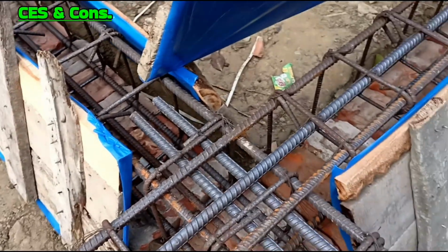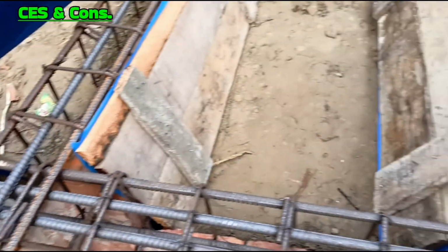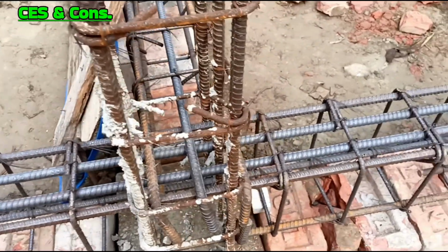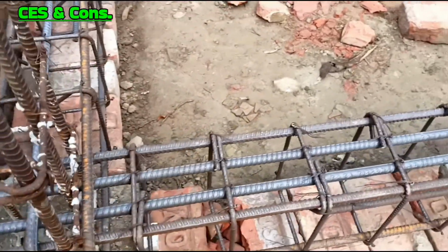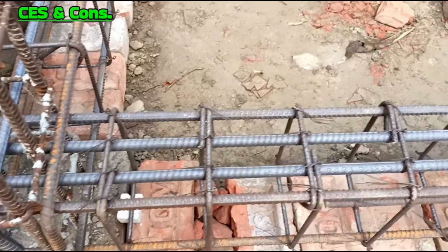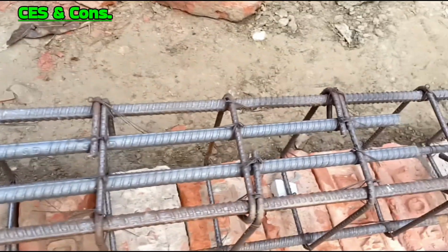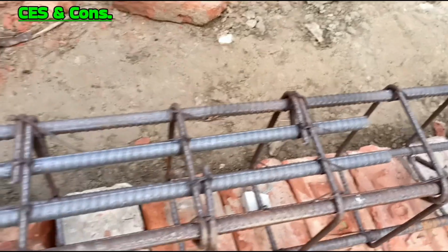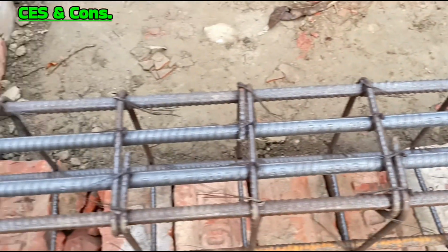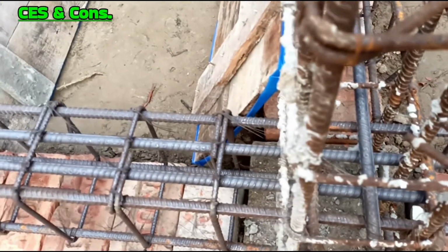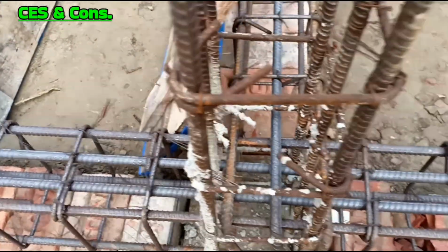Now I am stating a very important point for which we have to provide main reinforcement bar at top and bottom, both faces of the beam. Main bars are required at both top and bottom of the plinth beam when it is connected to RCC columns. This is because the beam experiences bending moment and forces that vary along its span, and these forces can create tension on both the top and bottom at different points.